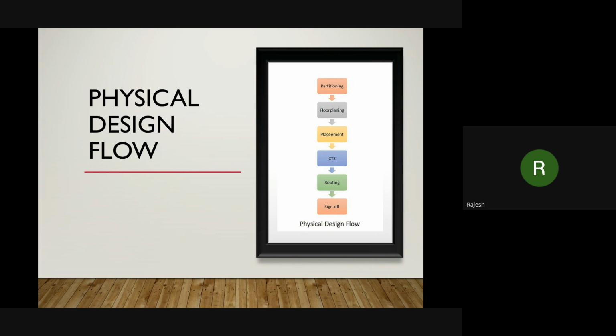You design something and check it, and if it is okay, then you look forward, and again you have to go back for something else. Everything will be done and redone, like everything will be automated, repeatedly, until every violation remains zero, there won't be any issues in your chip, and everything is fixed properly. Then only you can move forward. So that is why it will take more than 6 months, or even more than 8 months, to do the PNR for one single block.